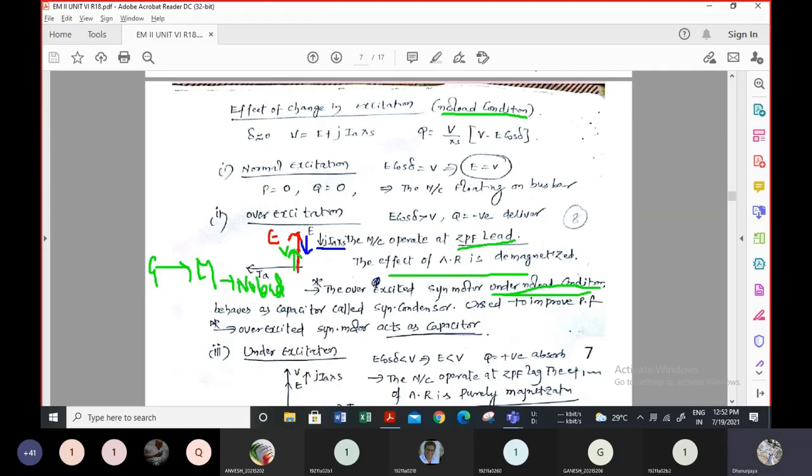What's the use of converting? We just interchange the power connection. So instead of a generator, I convert the Srisailam power plant machine into a motor and operate it under no load condition. And I'm giving over excitation, that is, a field supply value more than the actual value. Why?